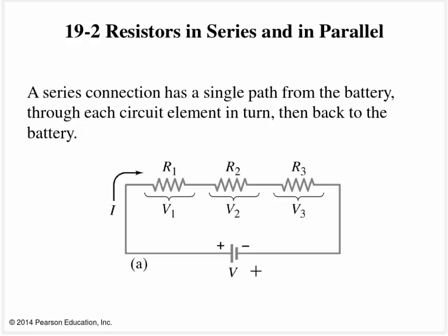So now let's take a look at hooking up circuits with, in this case, resistors in series. That little squiggly guy right here represents a resistor in a circuit diagram, and we'll say it has some resistance R1. Now here we have our EMF source. Since it doesn't have an internal resistance, the terminal voltage is just the same as the EMF, so we just write a single V here. And we know that current is going to flow away from the positive and come over here back into the negative. Now think back to the water pipe analogy.